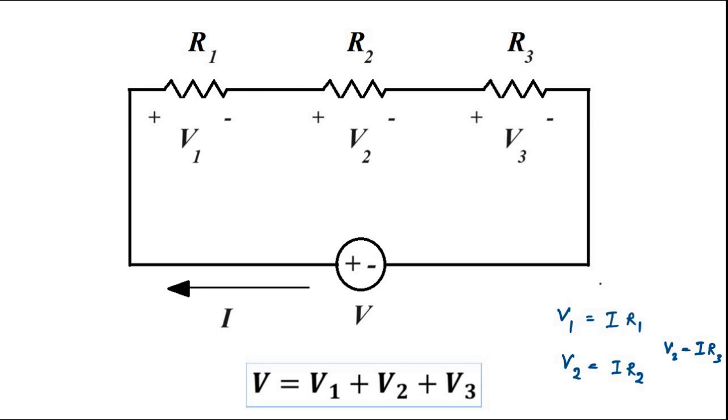That is the thing, and you have to pay attention to what sign you use. So here I have used the second sign dominating method. By that I mean, while applying KVL in a particular direction, whether it is clockwise or anti-clockwise, I have always used the second sign that is coming. Here the second sign is positive for the voltage source, and for the voltage drops the second sign is minus.